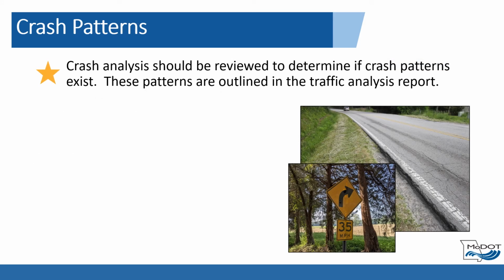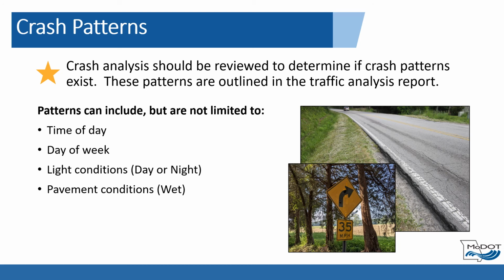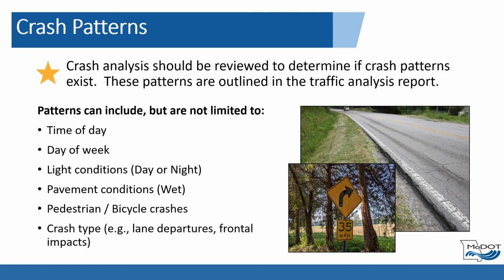The crash analysis should be reviewed to determine if specific crash patterns exist and are outlined in the traffic analysis report. Crash reports should be reviewed as needed to determine location and accuracy of information. Patterns can include, but are not limited to, time of day, day of week, light conditions, pavement conditions, pedestrian and bicycle crashes, and crash type.